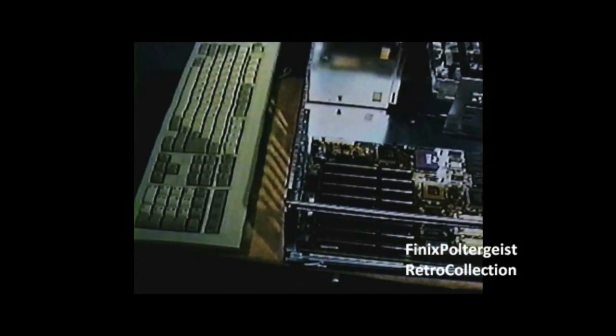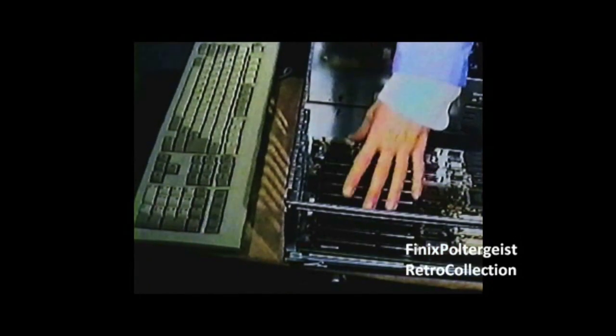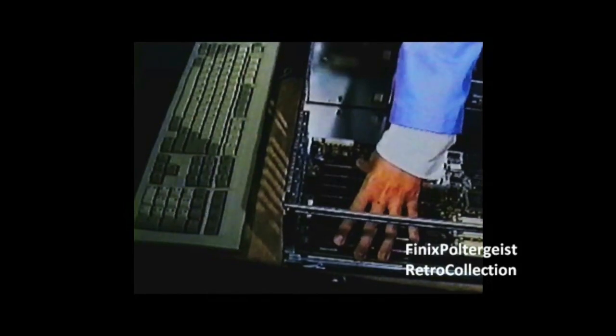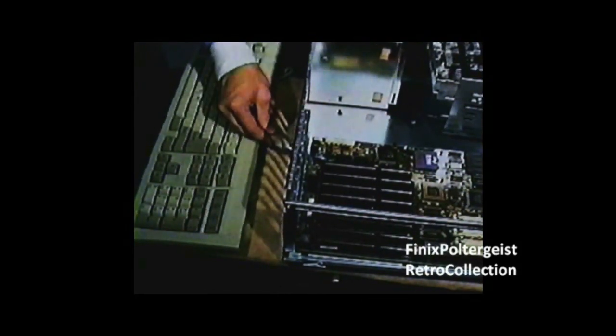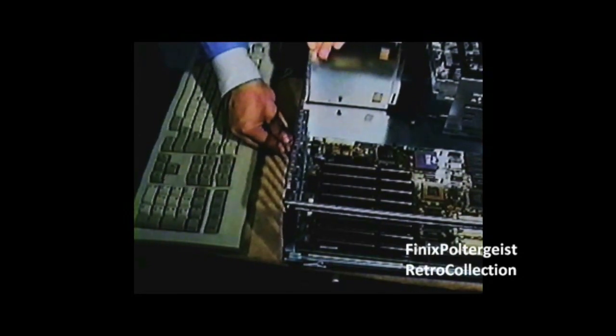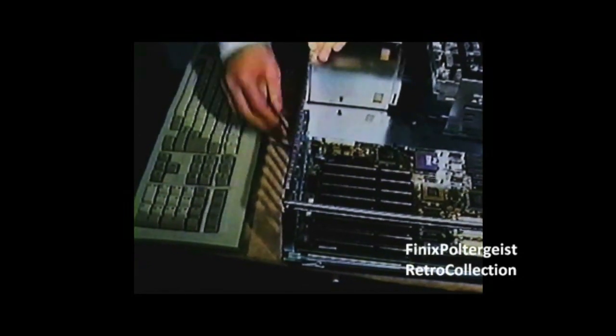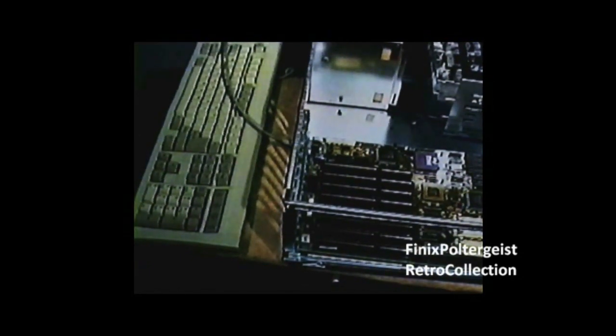Check your work in 2 ways. Make sure the motherboard is stable and cannot be shifted. Then, plug the keyboard into the keyboard socket to make sure the motherboard is aligned properly with the case. If everything checks, remove the keyboard. If not, realign and resecure the motherboard.